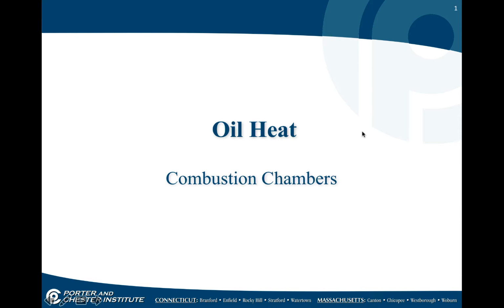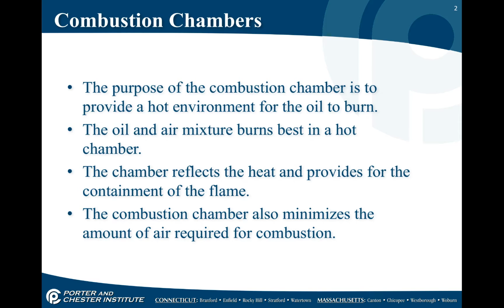This is a presentation about oil heating and combustion chambers. The purpose of the combustion chamber is to provide a hot environment for the oil to burn. What we do is we take oil and air, we mix it together, and we know it burns best in this hot chamber. The chamber reflects the heat and provides for the containment of flame. The chamber also minimizes the amount of air required for combustion because it keeps everything in one location.